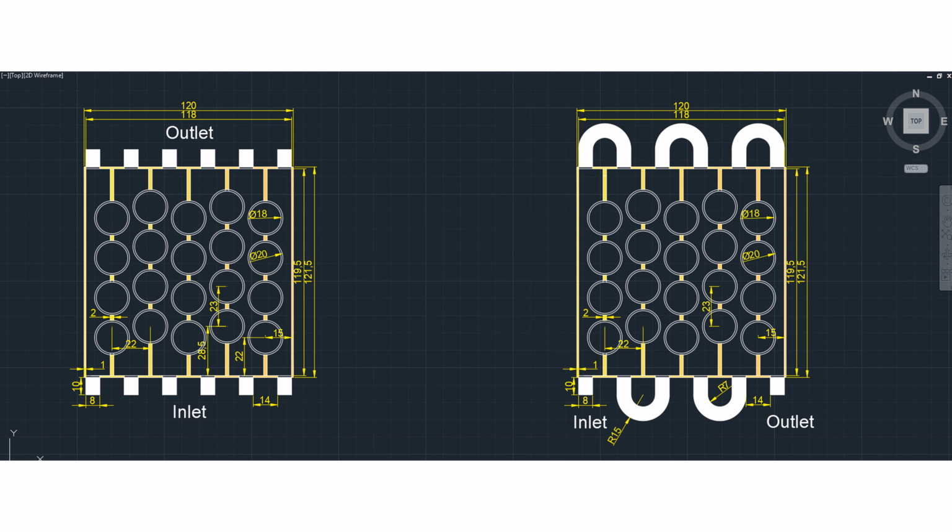So first of all, open the workbench window. On the left hand side we are observing the geometry that we are going to prepare first, and simultaneously we'll go with the second, which is on the right hand side. To give the details of the geometry, there are cells of 18 mm diameter and 65 mm height, and there is a casing around it that is a 20 diameter. Then the distance between the two cells is 23 in the vertical direction, and in horizontal it is 22. So they are not uniformly placed, they are placed like a serpentine channel.